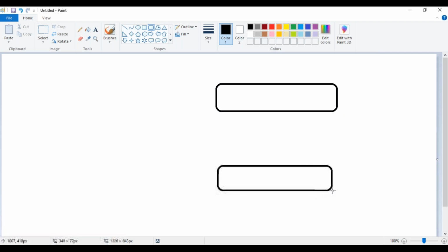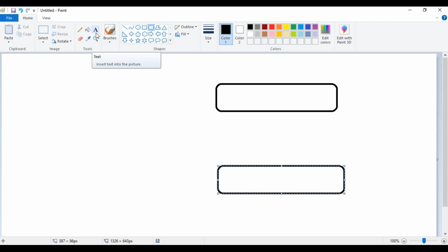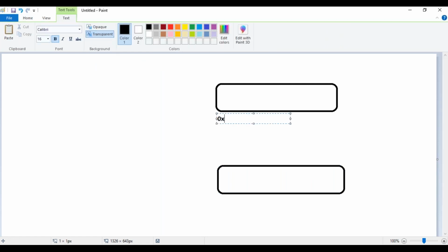There are two addresses per register. You don't look at the second address because that refers to the instruction set, the ones you don't use to handle data. So that is to handle the instruction. Don't look at the second address, it is always the first address you have to see. There is a register at the address 0x06. So 06H means hexadecimal.